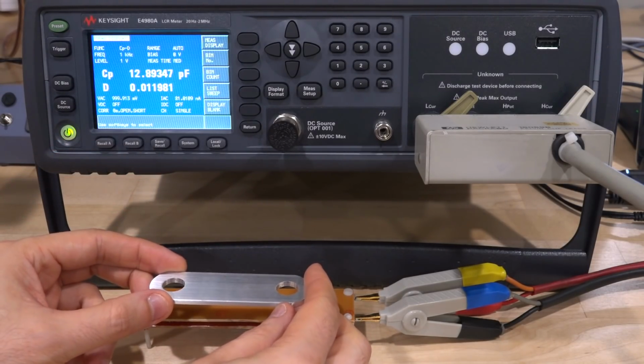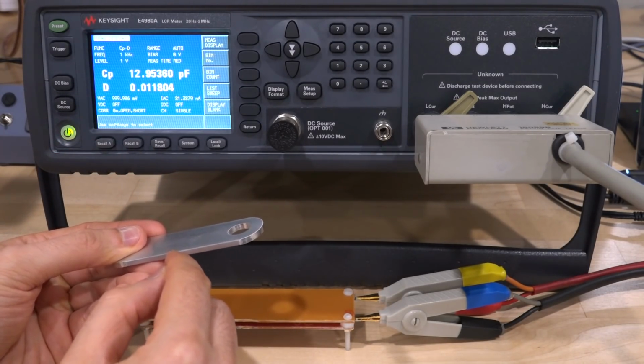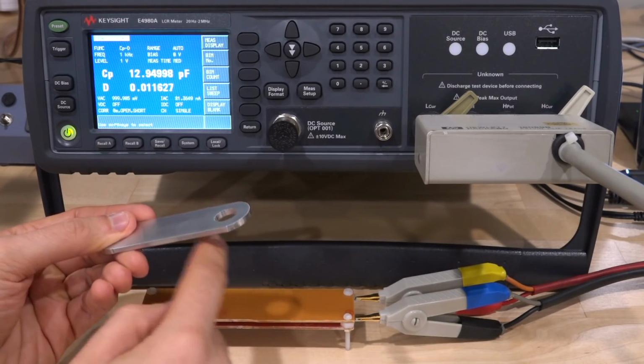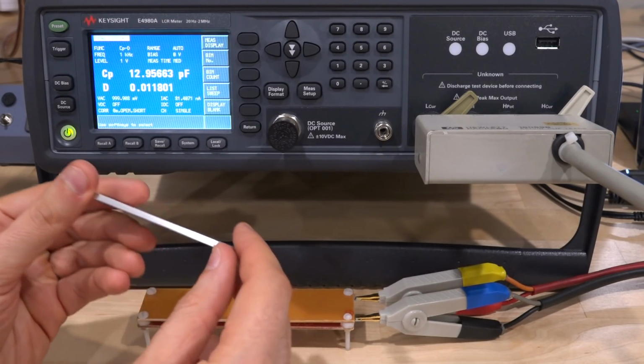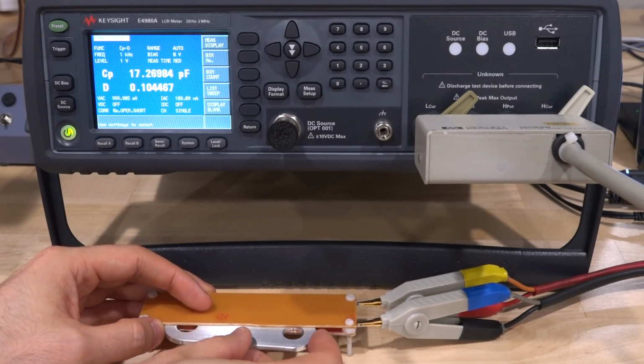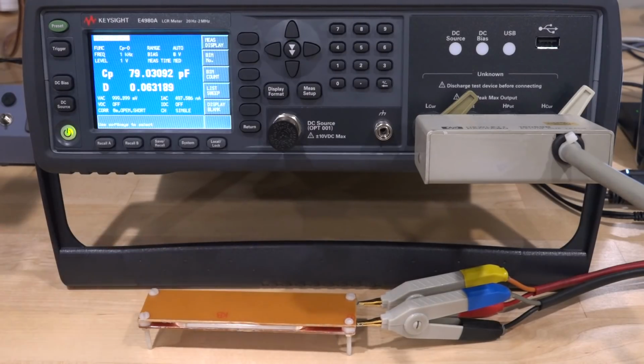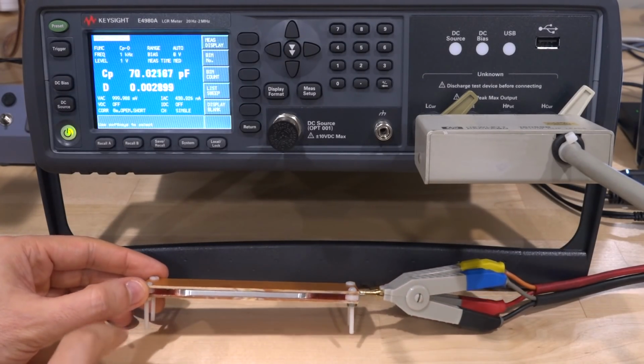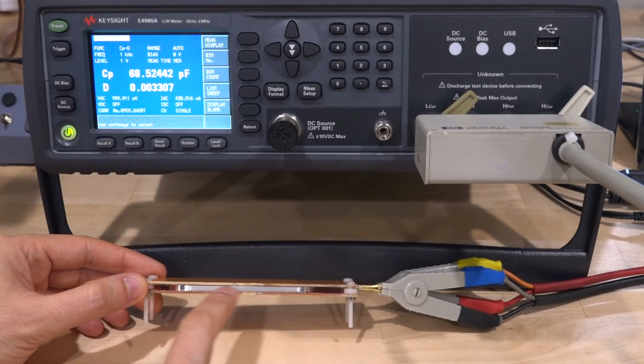So what happens when you put this in the middle? Well, if there is no electric field through it, you only have electric field above it and below it. So you actually are going to create two capacitors. Let's see what happens. Push this in the middle, like so. Look at that. 73 picofarad, a significant increase in the total capacitance here. And that's not surprising because if you look, there's no air gap left where this piece of metal is inserted.